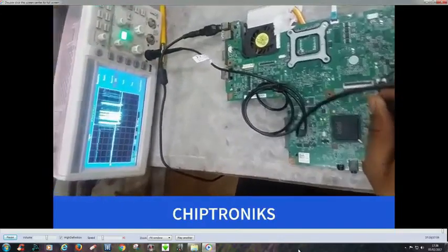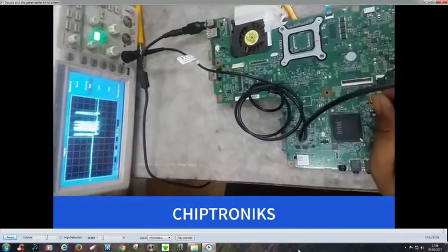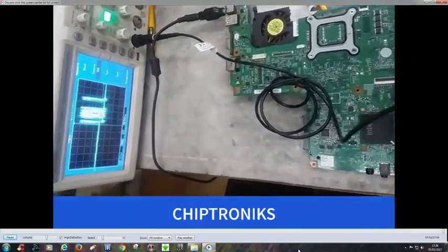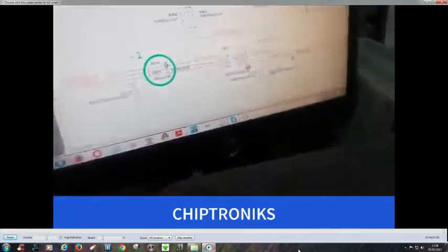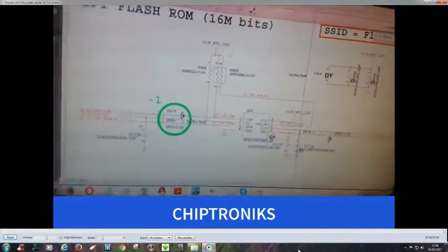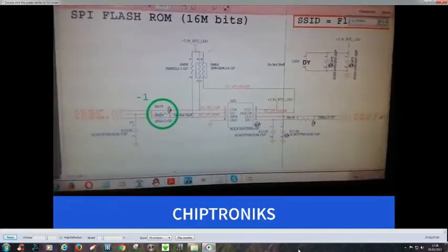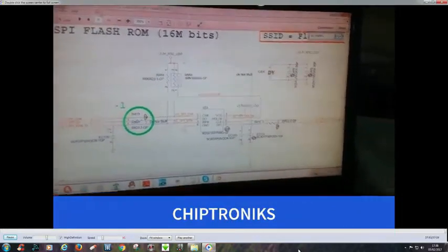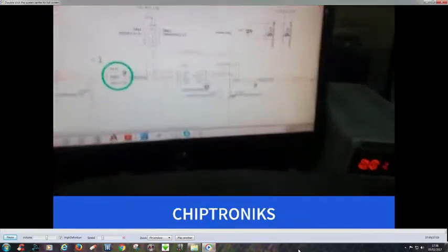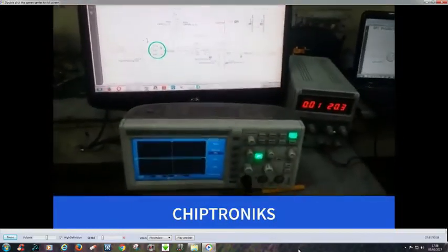So this is the way to check the interaction of the IO controller with the BIOS chip. If all those four things are working properly, then the microcontroller inside the IO controller will generate the S5 underscore enable. And in my next class, I will extend this discussion. Thank you for today's class.